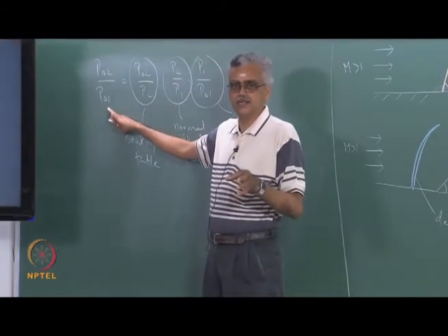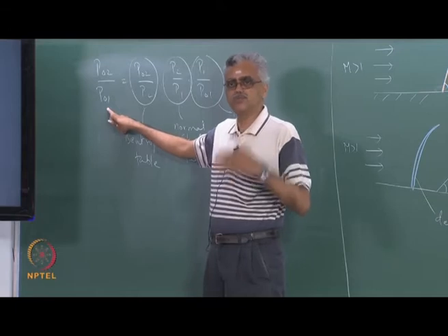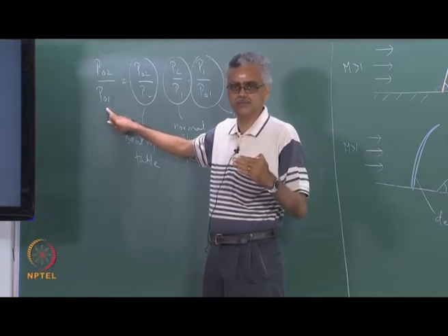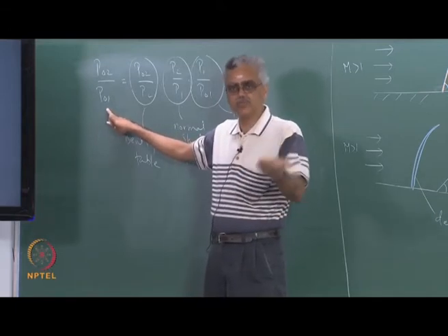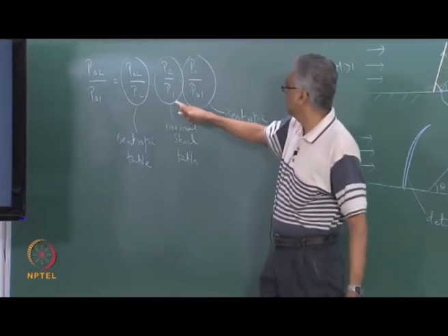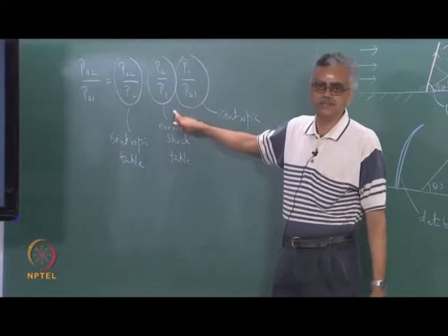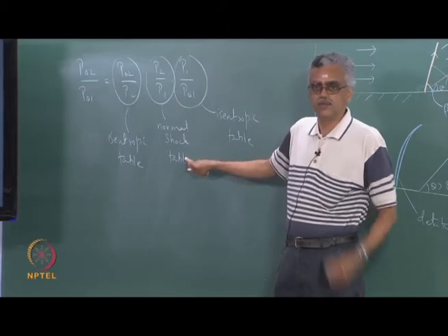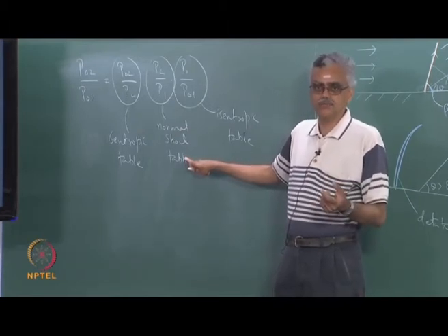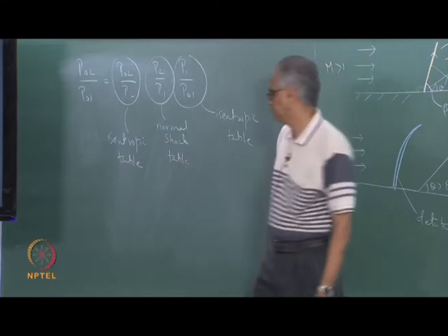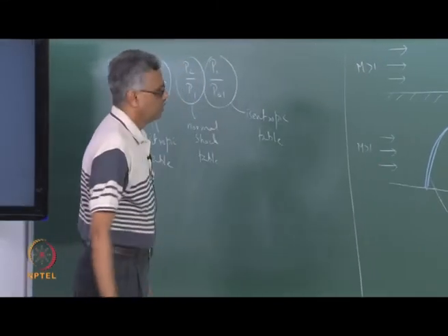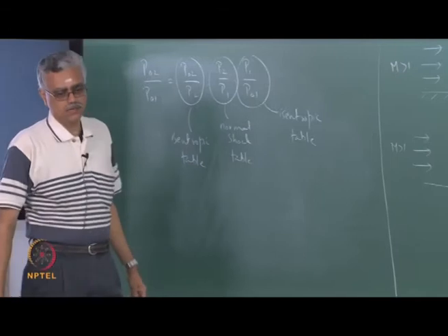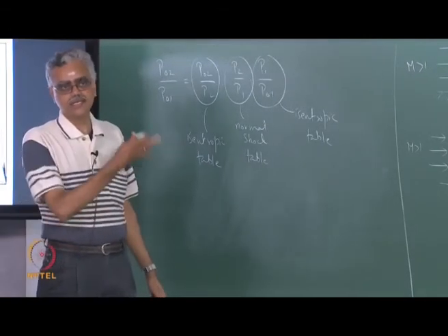It is true that the loss of stagnation pressure comes because of the normal shock component, but the value happens to be frame dependent. Remember, we are able to calculate this without any difficulty. So, we are accounting for that, right? But the value depends upon the frame. So, what we will do next is work out several examples illustrating these ideas.